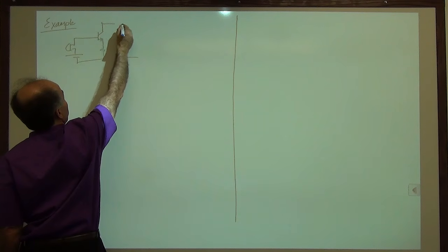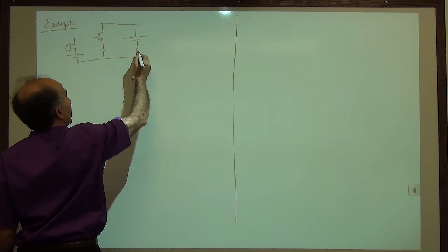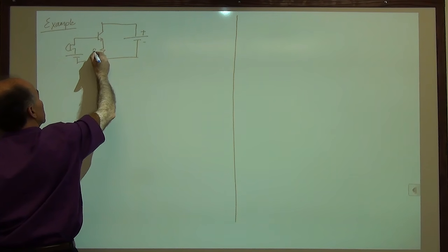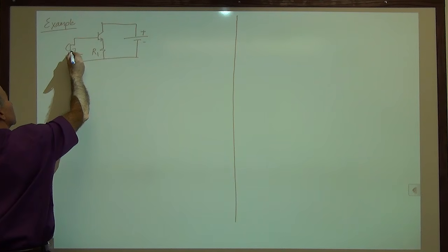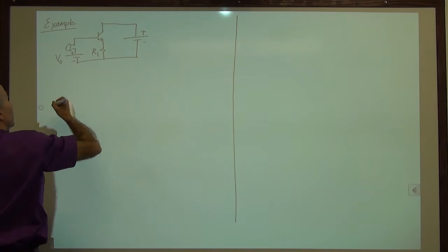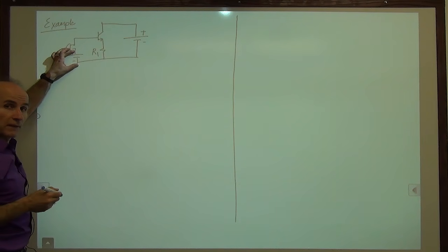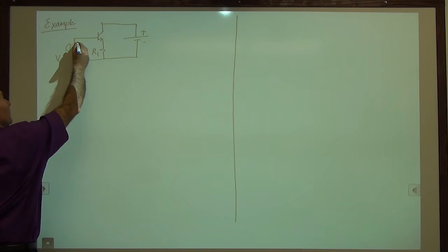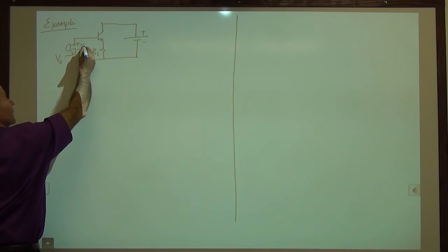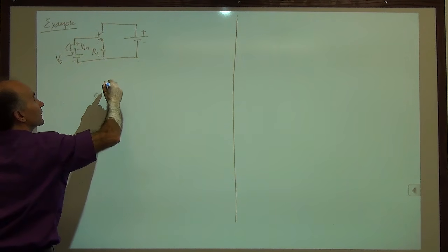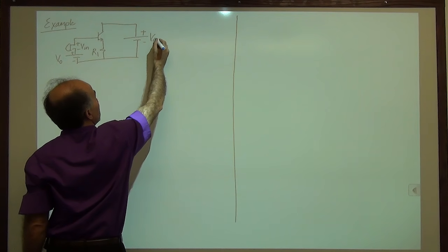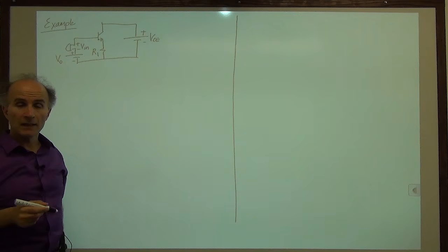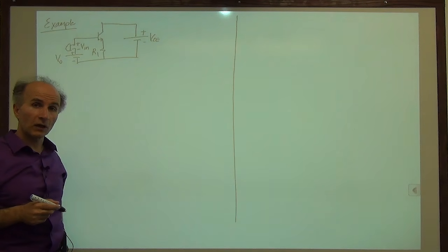This is a circuit that we briefly looked at before, and we saw that the calculation of the current was a little difficult because we had to iterate. So we have a bias for the base emitter equal to V0, or a bias for this overall potential. Then we have a signal from the microphone. We call it Vin again. And we have a battery here, VCE. And then we would like to construct the small signal model of the entire circuit.